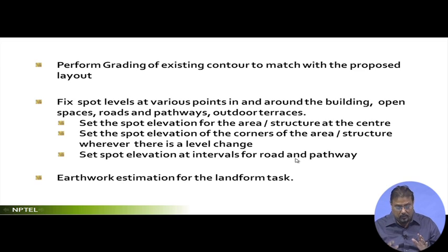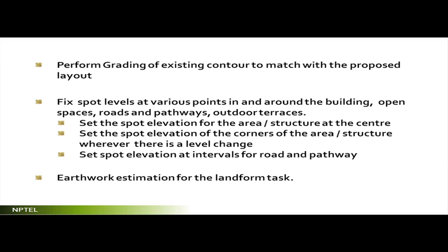So now if I summarize, you have got a project in which in the landscape you are trying to make the landform design, and for the landform design first you have studied the soil types, and you will make different divisions of the soils. Once you have done this, you have got the existing contours and the slopes. Now you are going to change it. Once you are going to change it, you are making different profiles, and then naturally you are changing the levels.